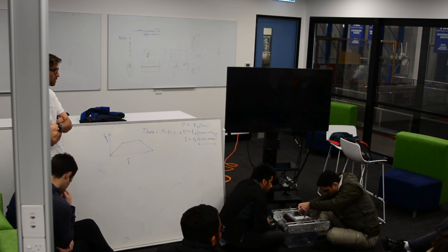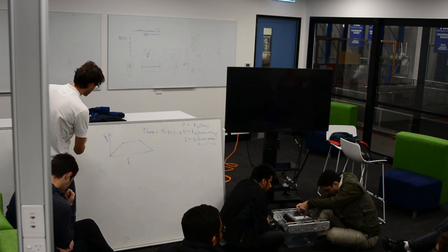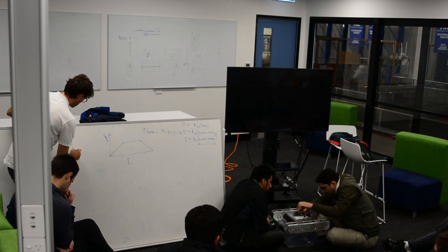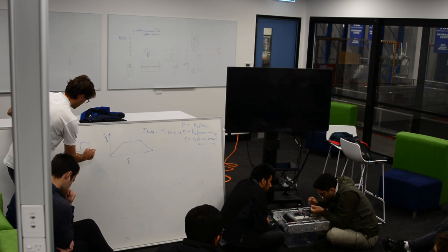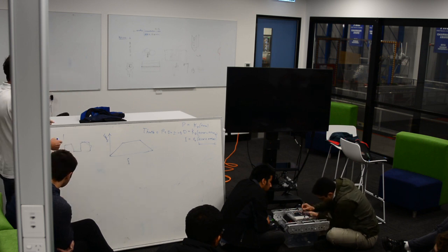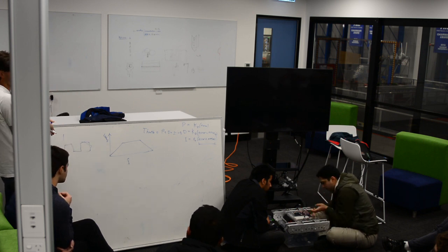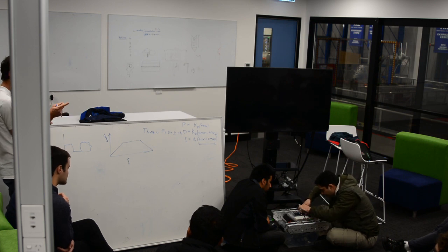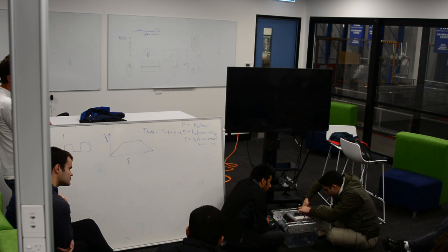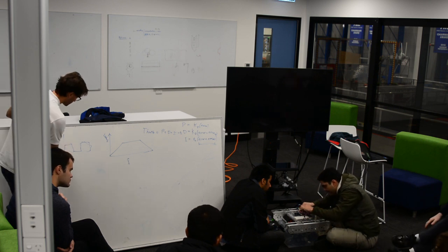So you've got these ticks coming in from the encoder. If it's going fast, they're coming in fast, and if it's going slow, they're coming in slow. Explain your thinking again. Well, you can break it up into blocks and check how many ticks you've covered over the runtime of that block of program.